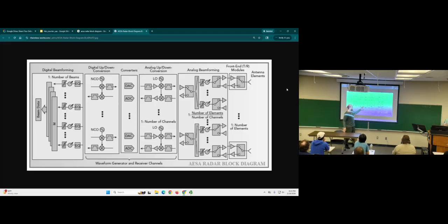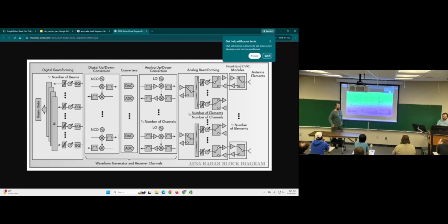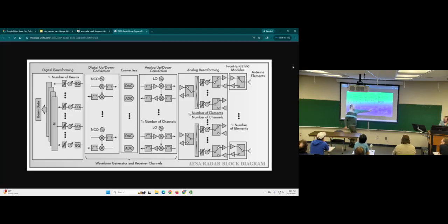But the whole point of this is, you want to form a beam in X direction, so you send a whole bunch of this data to these antennas at once and control them simultaneously. The frequencies and modulations are just a property of the signal. From an ESA perspective, that does matter, but in this context, the thing that matters more to actually aim and direct it is amplitude and phase. So it's just controlling these two things.